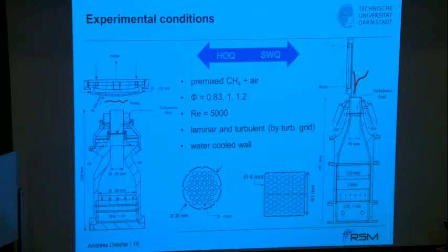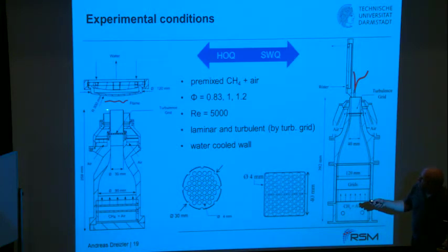And that is these 2 experiments. Both are based on this kind of contracting nozzles. I haven't detailed that previously. These contracting nozzles are intended to provide a top hat flow coming out of that nozzle. And then you can insert a turbulence generating plate or not. And then you create here a propagating flame that is then traveling or approaching the wall. And here you see typical